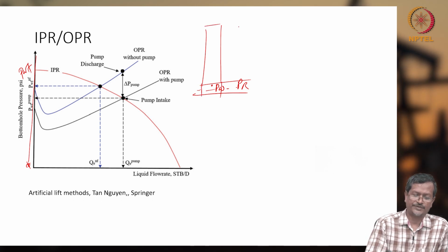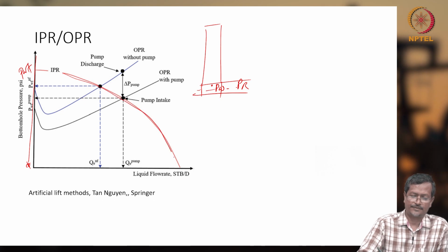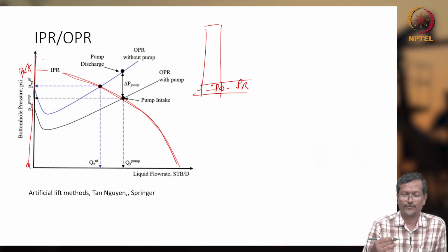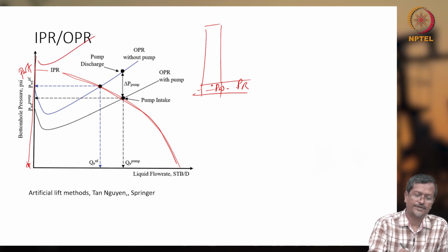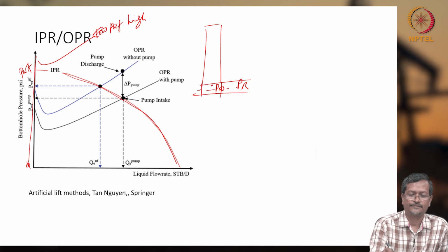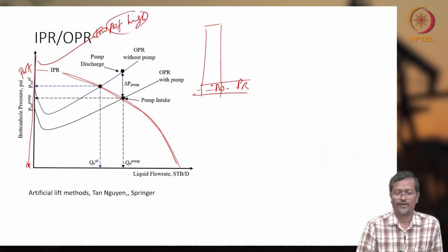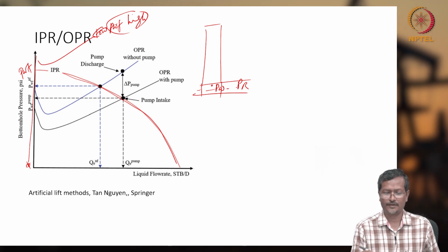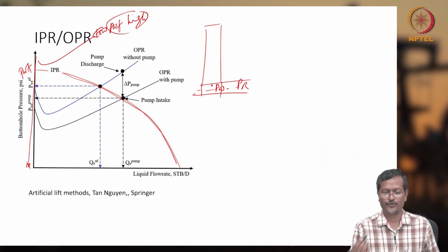Now you have the inflow performance relationship. This is IPR. We are assuming this is curved, and if I have very low pressure, fluid PWF is unable to produce any fluid. Let us say the initial condition is this one, PWF high. So, PWF high means it will not give enough flow rate, or it will not give any production.